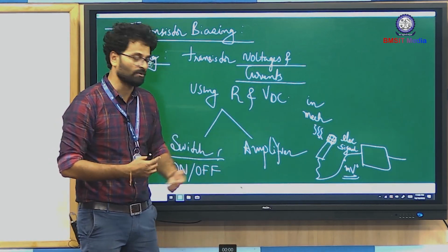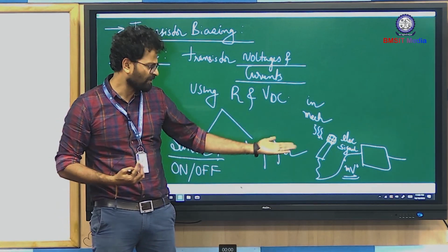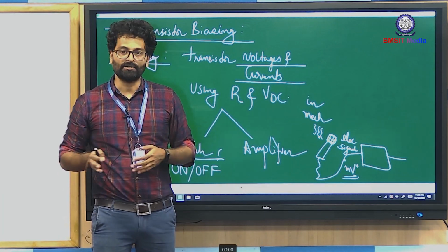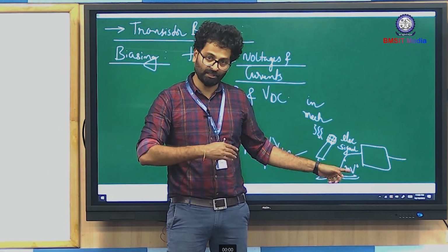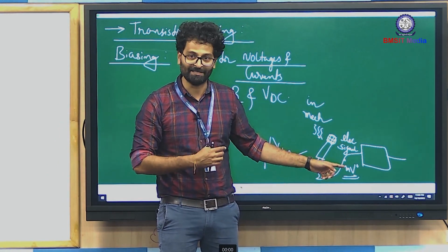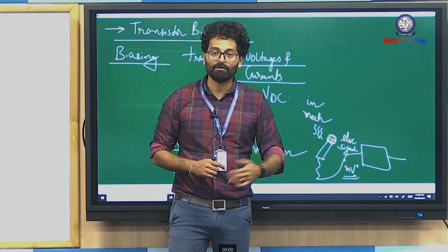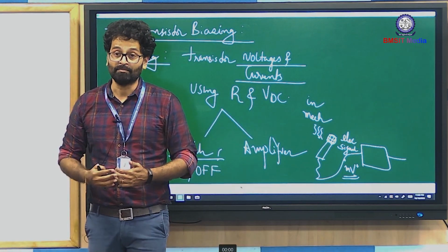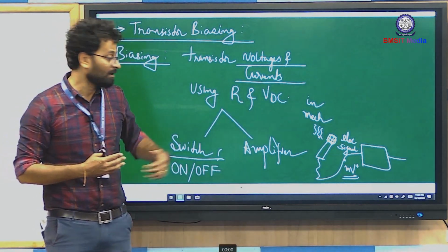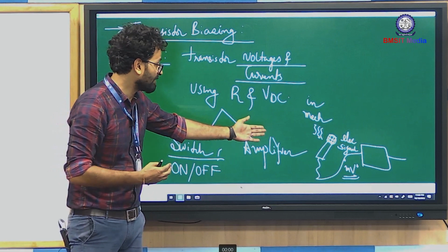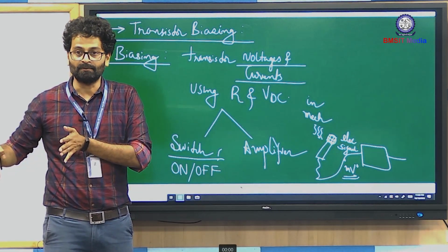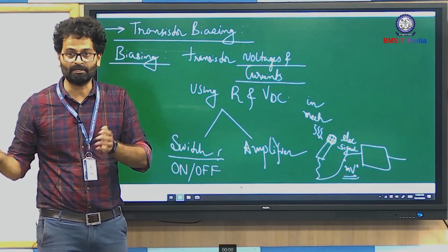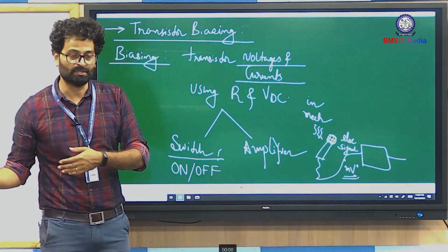For that, you can use a power amplifier or an audio amplifier. An audio amplifier increases the voltage level of a weak incoming input signal, and a power amplifier amplifies the power level so that the signal coming out of the microphone can be easily fed to a loudspeaker. Loudspeaker is nothing but the music system you use at your home.